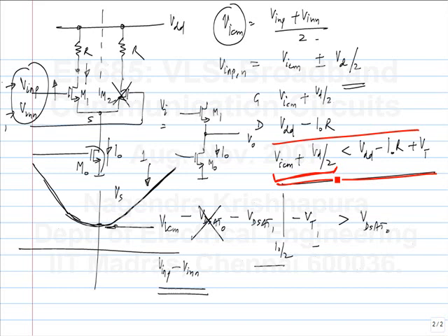Now, is the question clear? This side is the high level voltage that appears on each of the input lines, okay? And this side is of course some voltage that is based on this circuit analysis. Now, what is the reasonable value for this voltage? VDD, right? So, when this logic gate is giving you a high output, one of these is at VDD, the other one is at VDD minus I naught R. So this is nothing but VDD if a similar gate is driving this.